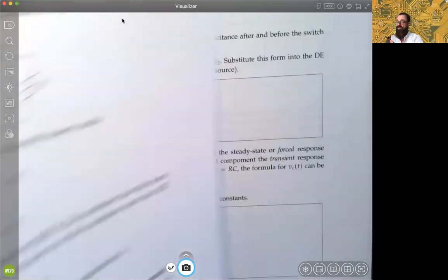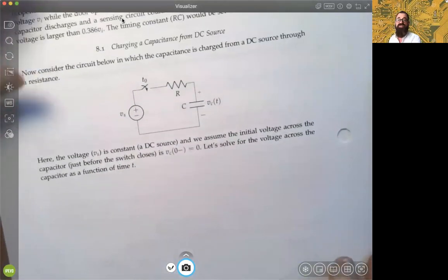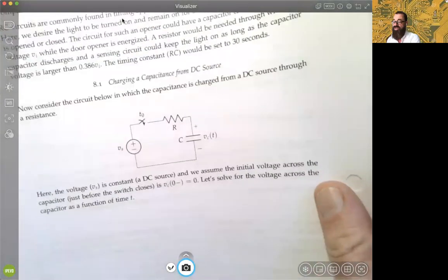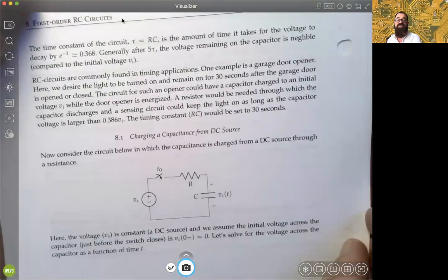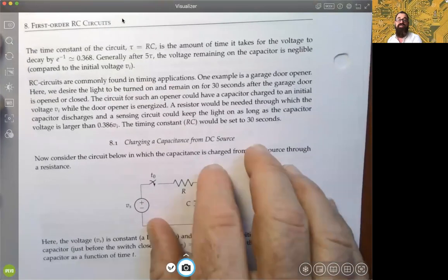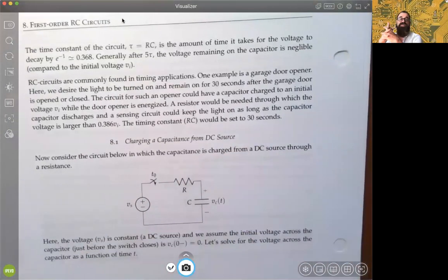All right, so if we flip over to page 96, a couple of other details, just indicating in words what I just mentioned. That tau value is called the time constant. That is R times C. And some people would say, of course, it's the amount of time it takes your voltage to decay, because it is dropping. And because it's dropping exponentially, decay functions are usually represented by exponential functions. Sometimes they use that word decay. And we know the reciprocal of e is 0.368.